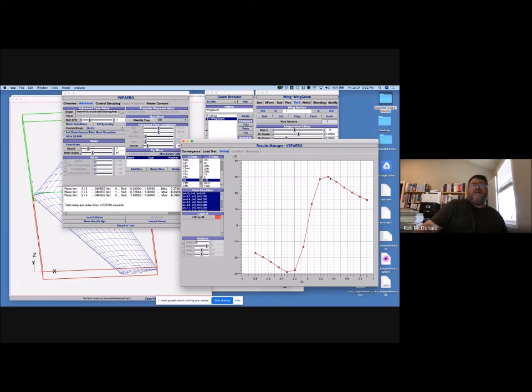And you guys are giving me some ideas for changes to make to VSP right now. So what I'll say is you'll need to iterate, and you'll need to think about what you can change as an engineer, right? As an engineer, you can change the wing area, and you can match that to the speed you want to fly and to the wing area you have, and that'll help. It'll actually move this peak in L over D left and right. By changing the wing area, you're going to move this peak left and right, and this horizontal axis, CL, controls speed, so that'll control the speed left and right.